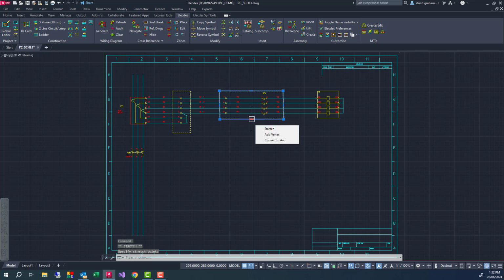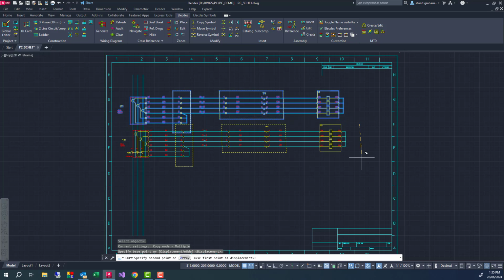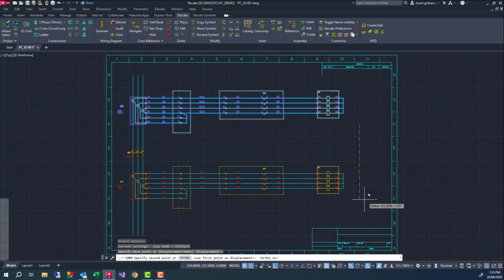This completes my AC-CT circuit. Most of the time, a designer will not need to create circuits from scratch. This only needs to happen the first time a circuit or a part of the circuit is created. I wish to have CT inputs on both sides of my circuit breaker asset, so I can simply copy my AC circuit.